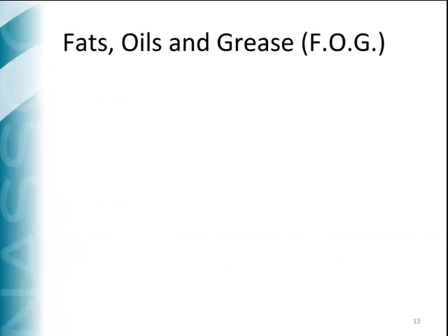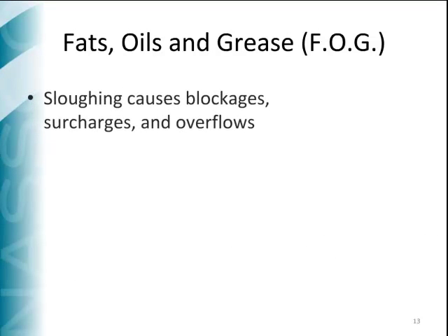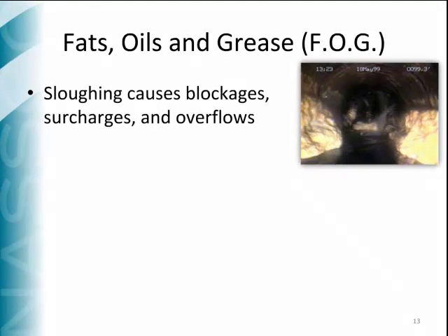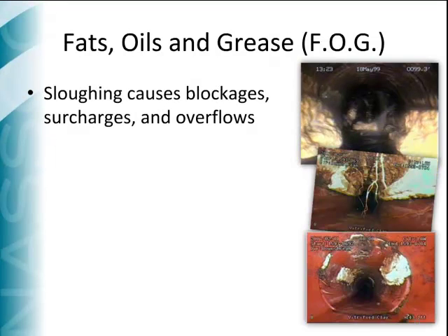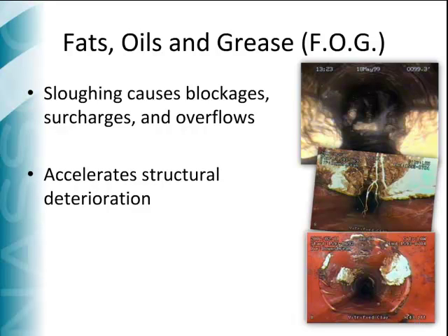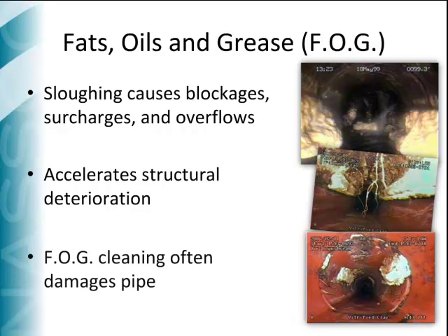Fats, oils, and grease deposits. The accumulation of grease often produces blockages. These types of blockages can cause backups and overflows. Grease can also accelerate structural decay. Aggressive and repetitive cleaning to remove grease may induce pipe deterioration as well.